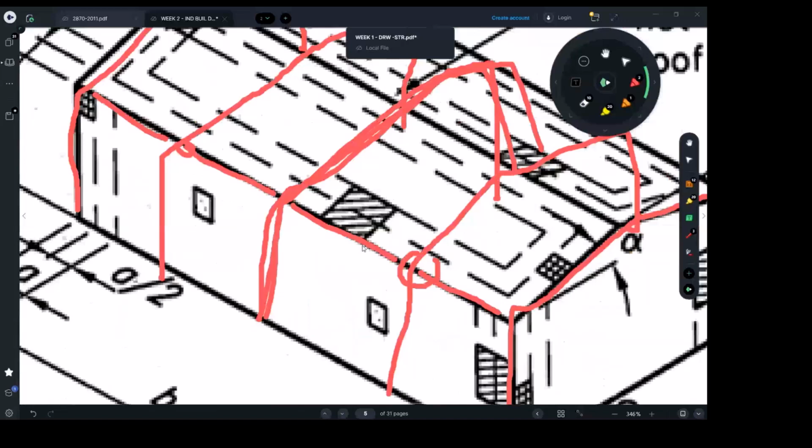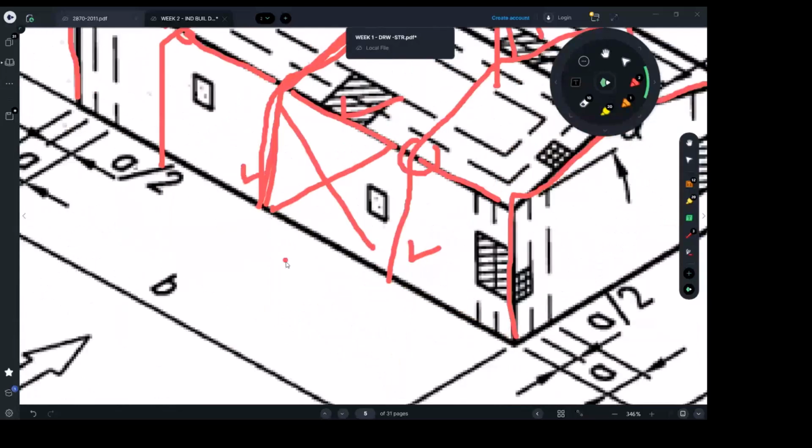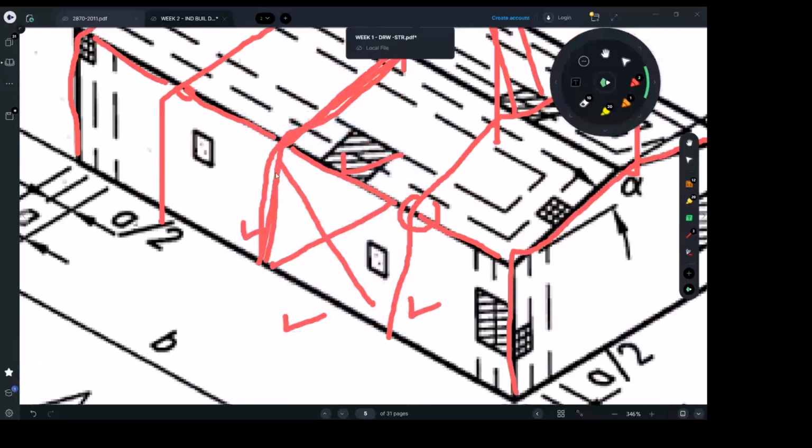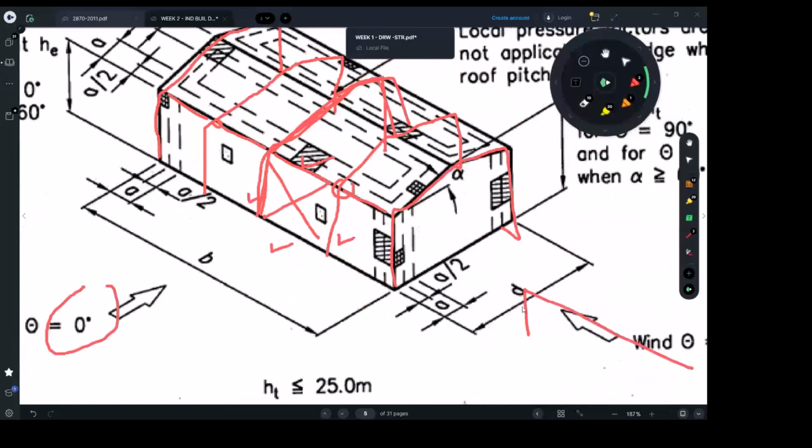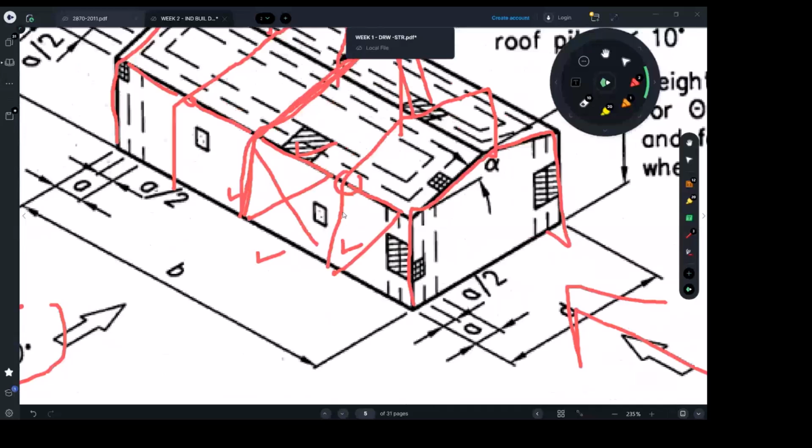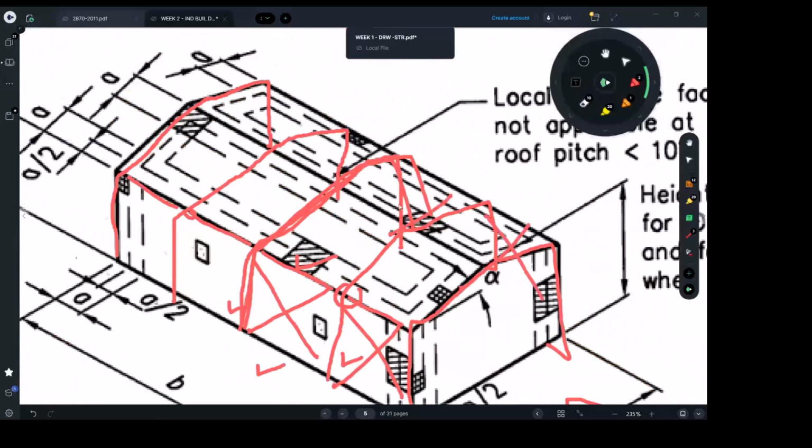And then we're going to introduce some X bracing. The X bracing is going to work with the eave beams, the eave H beams, and those columns and the ground, using the truss principles you studied at university. There is a truss system, so you can see this triangle. Simply, in case there is a wind blowing this way, you're going to have the portal frames or the structure stabilized. So you're going to have bracing here, and the same thing, bracing on the other side.